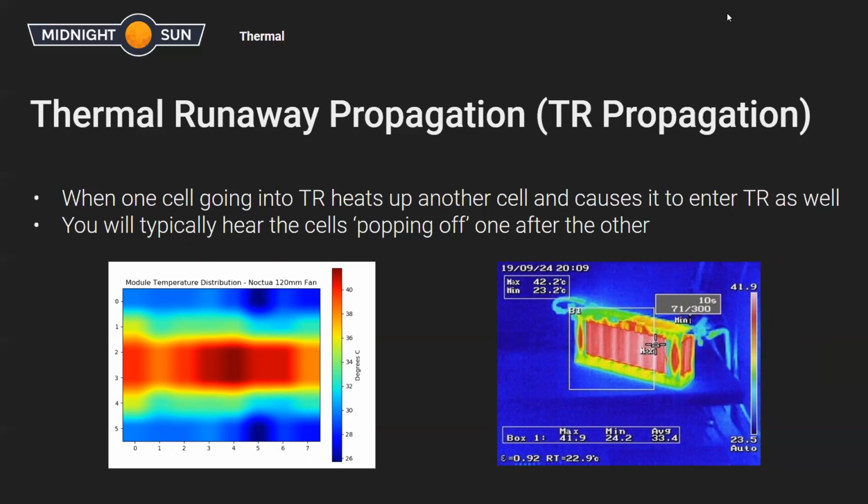And that test was just with the nominal current draw that the data sheet suggests. So that indicated that we do have to look into cooling and make sure that we're adequately cooling the cells. And on the left there's temperature distribution within the pack. The cells on the outside were a little bit cooler than the cells on the inside. So with that data, we decided to make some changes in the modules and allow for some more airflow into the middle section of the battery pack.